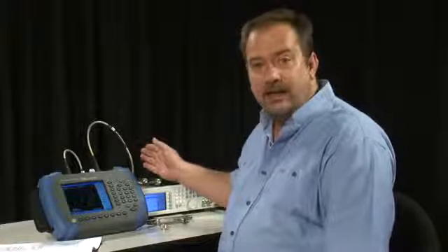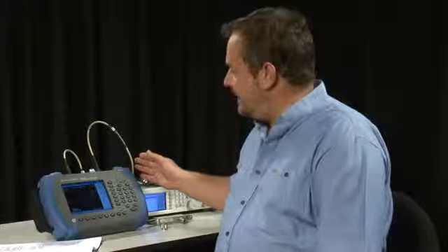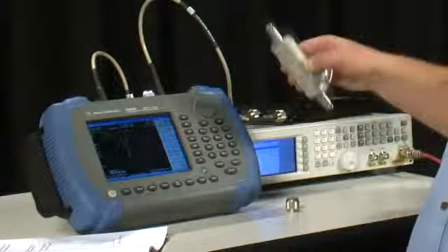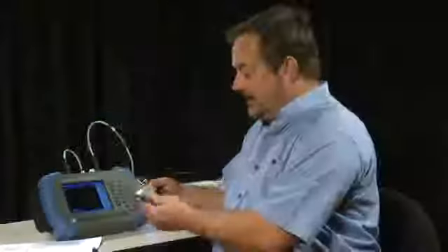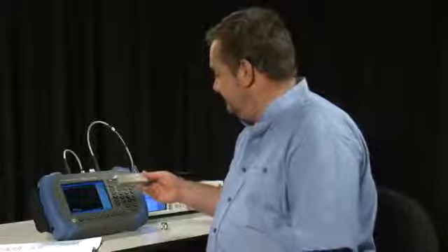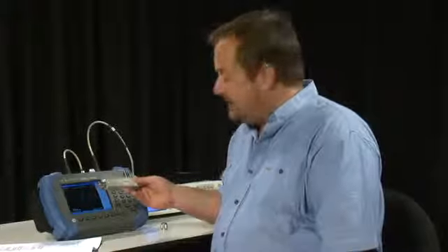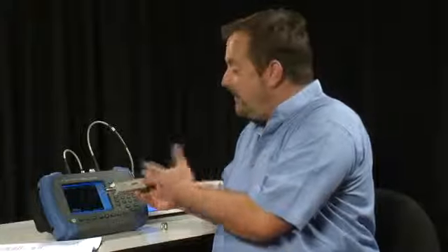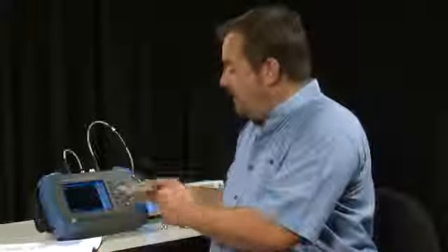Now, another measurement that you'll frequently find you need to make out in the field, besides measuring the frequency response of a diplexer to check that it's tuned up properly for the transmitter or for making adjustments to it, would be to measure the return loss of a device, either of a diplexer or perhaps more commonly an antenna. To do that, we're going to need a directional bridge, and here I've got an Agilent 86205A directional bridge, but any good quality bridge will suffice. What the bridge does is separate the reflected signal from the through signal, so we can measure the reflected or return loss of the device.